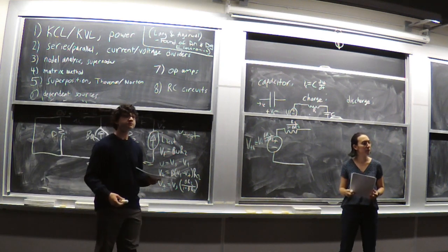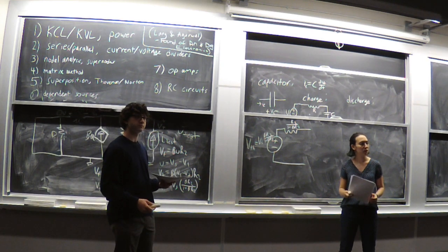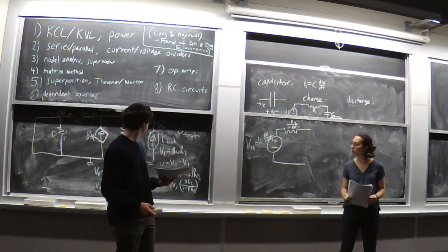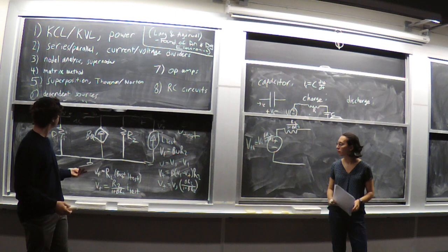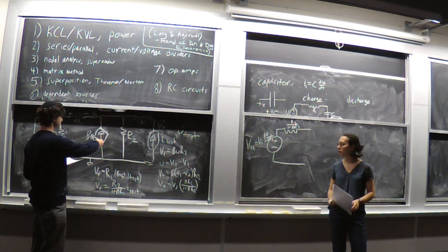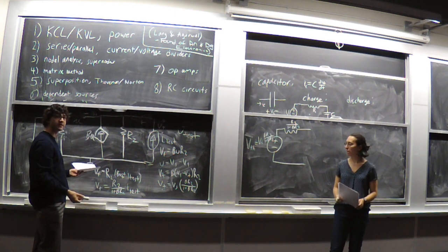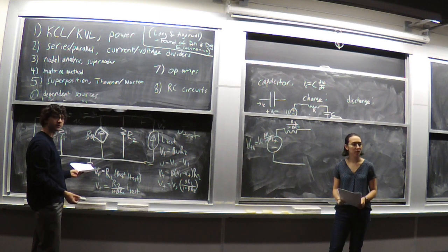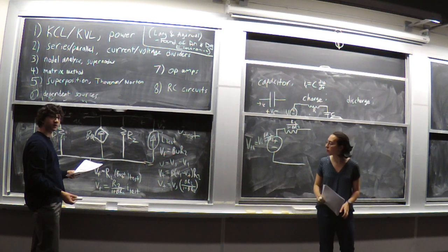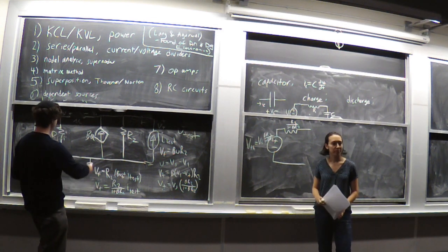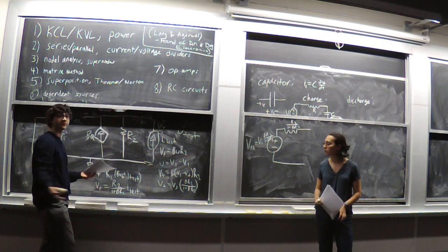Sorry, I'm a little confused why the Thevenin resistance isn't just R2. Yeah, it's a good question. The reason is that we get this sort of weird response from the dependent source here. Okay, so if that dependent source had been an independent source, would the Thevenin resistance have been R2? Yes, because then when we turned this off, we would have just been left with a resistor.